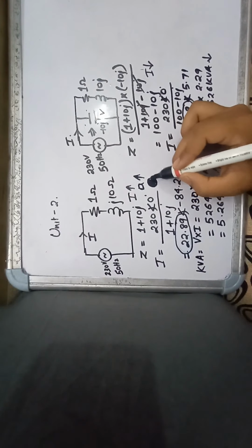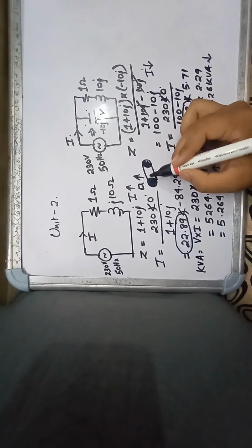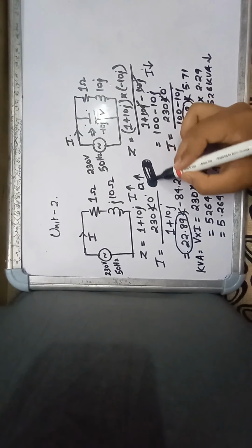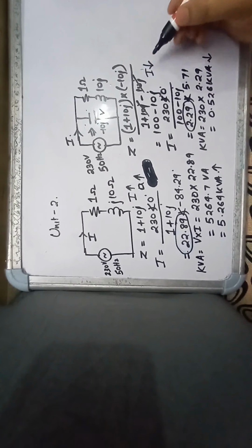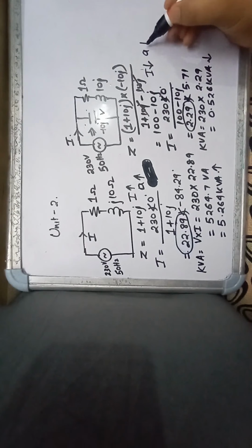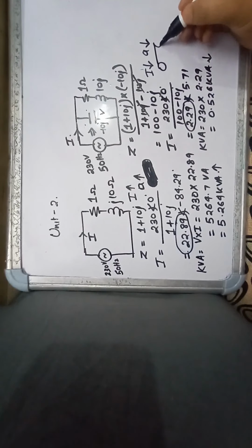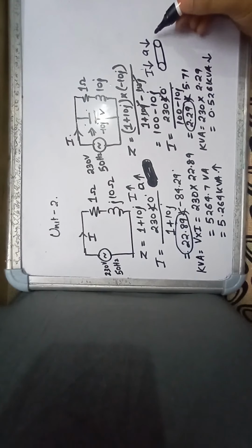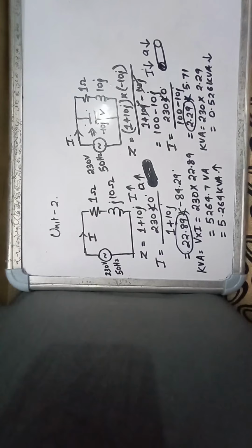Thick wire means you have to invest more on wiring, so it will be costlier. Here the current requirement will be less, so the cross sectional area will be decreased, which is more economical. Considering the current, it is more economical.